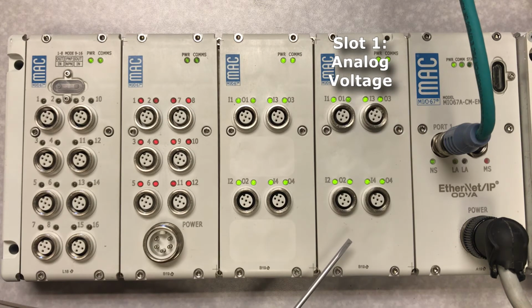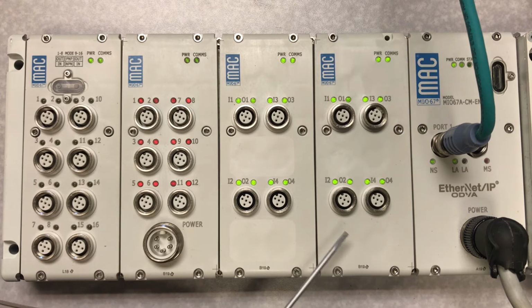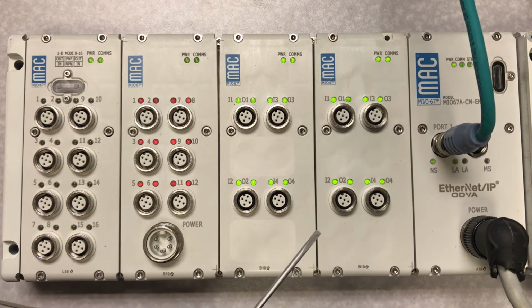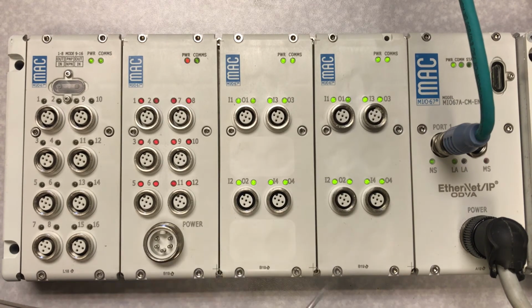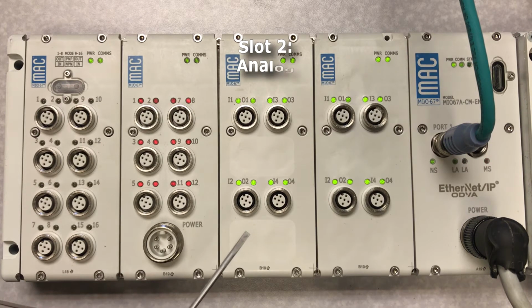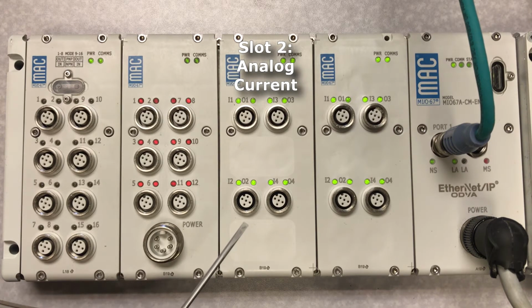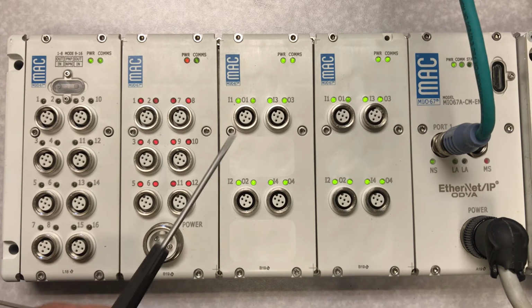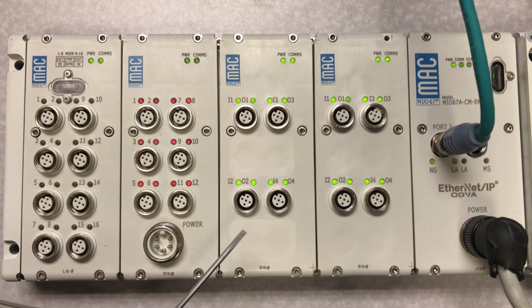This module is an analog voltage I/O module. It can be set up for input or output control out of one of 4 ports. The analog voltage module is a 0 to 10 volt control. The next module in slot 2 is an analog current I/O module. It can control inputs and outputs out of one of 4 ports. The analog control is a 4 to 20 milliamp current output or input.